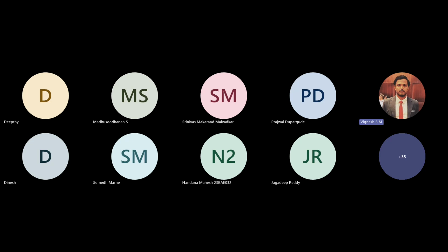First thing, we have to do local sizing. Please don't do global sizing. What I showed in the demonstration was global sizing, but I always recommend local sizing. What local sizing means is we have to do a fine mesh wherever it is required. Please don't make the complete domain a fine mesh. Do a fine mesh wherever it is required, and make the other regions coarse where it's not required.